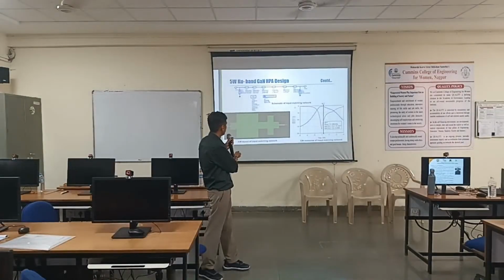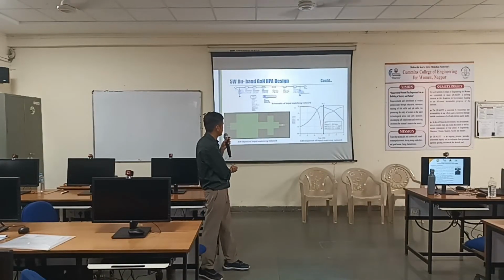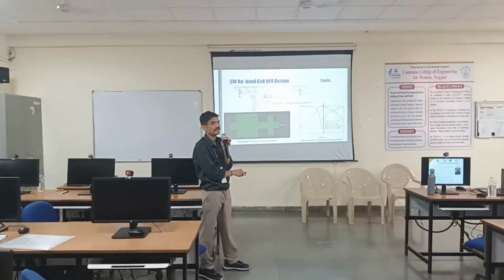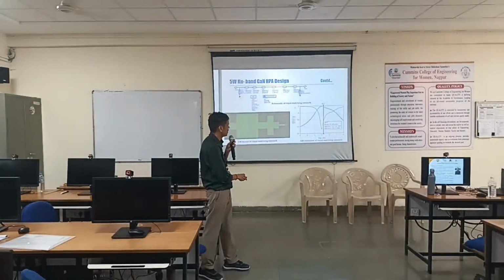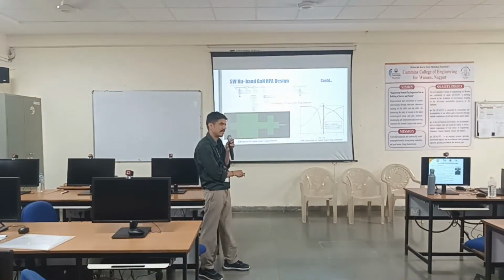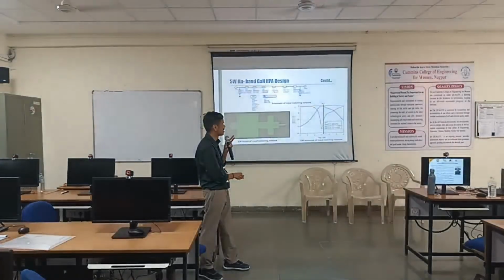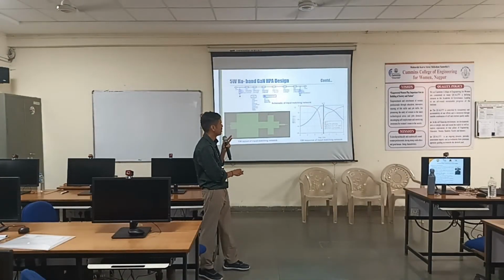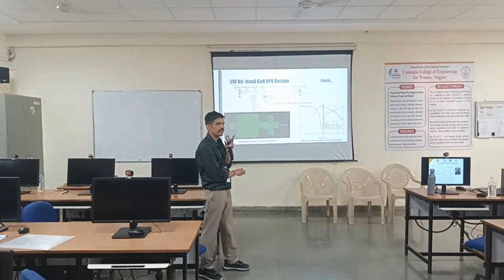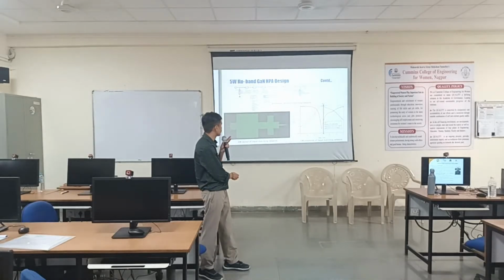Then I did the matching network design. So this is input matching. You see the width is changing. So this is input matching, and this is just the response of the matching network. And you remember this I did for Ku band. So the designer's life will be very, very complicated. Three requirements I have to meet: high power, high frequency, bandwidth. All these three requirements cannot be met simultaneously. So you see this response is very narrow band. And the gain is a function of the frequency. Still, I could achieve 200-250 megahertz of bandwidth.